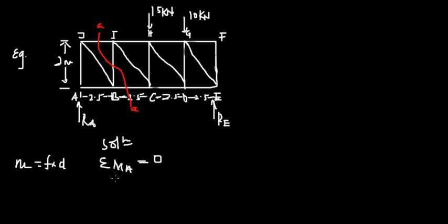Right, so let's proceed from there. Taking moment from here, we have these distances. When you sum these distances up, 2.5, 2.5, that's 5, 2.5, 7.5, 2.5, that's 10. So we have RA multiplying a distance of 10 meters, and then you equate that to your other reactions.